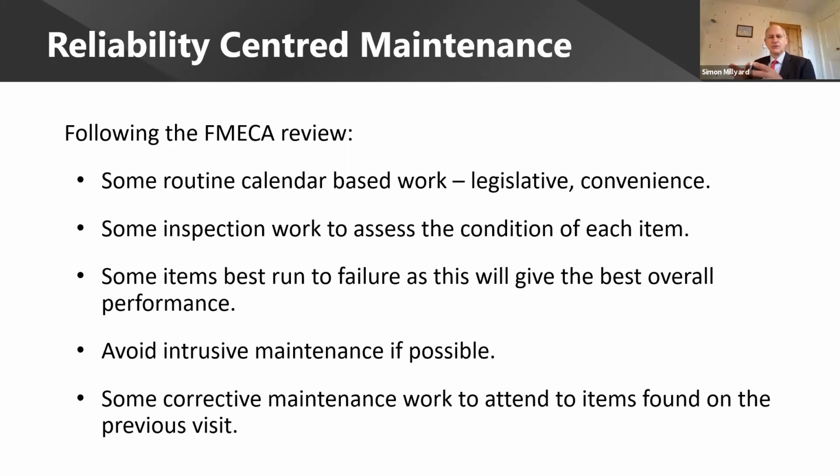I haven't put it up on the screen here, but many of you will be familiar with the bathtub curve of failures. This is a classic prediction that when you buy a new piece of equipment, it is more likely to fail than when it's been bedded in and running well. Then you'll have a long, long time of good performance until it starts to wear out, where you start to get some failures. So if you can get over the initial bedding in period, then you're pretty confident of a long run of high performance. So over 2 decades, you may well get better performance from some items if you run them to failure.